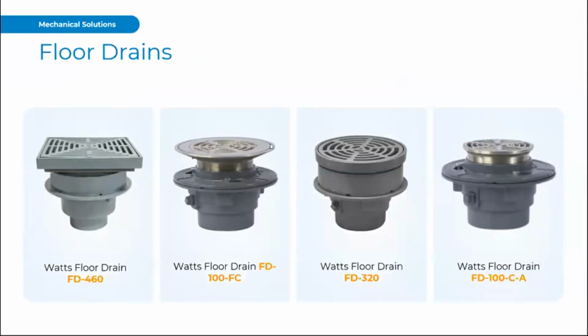membrane flooring unit used, as well as a lower membrane clamp. And it's the same body for both the 100 CA, which is your base floor drain strainer, versus your FC. So they're interchangeable. And this is true for your cleanouts as well. This is true for your square strainers as well. So you're using a similar floor drain body with interchangeable top assemblies.